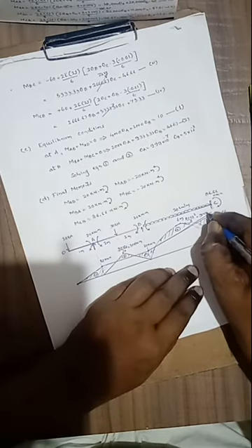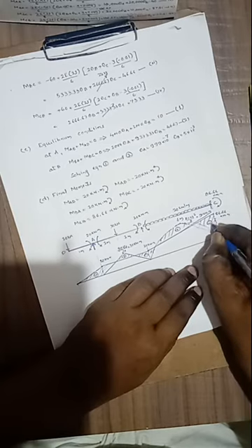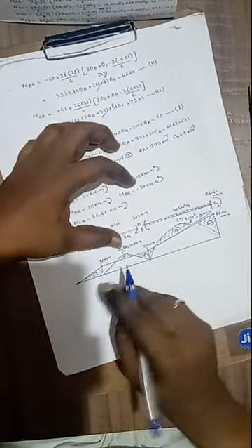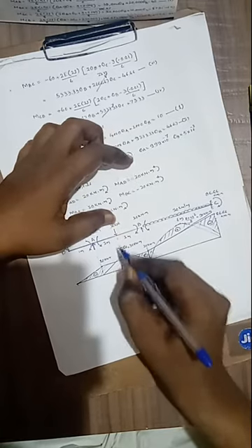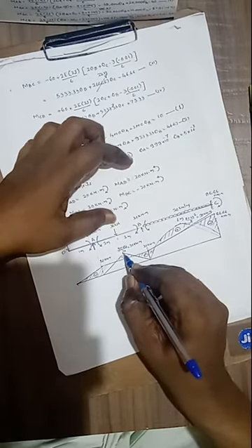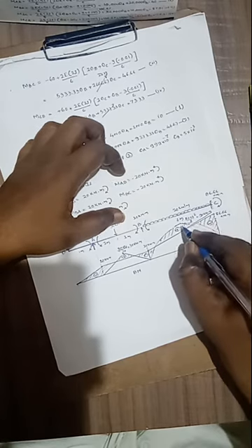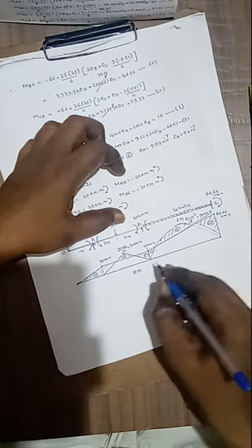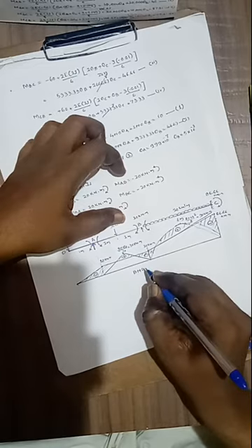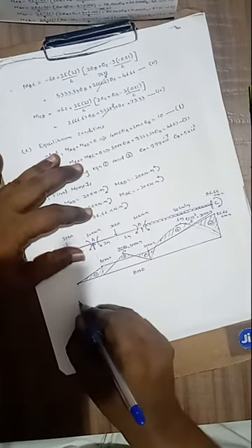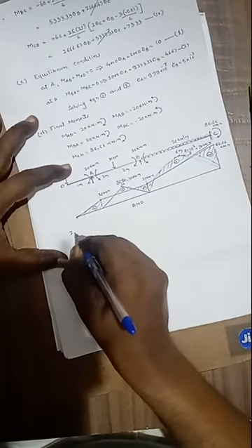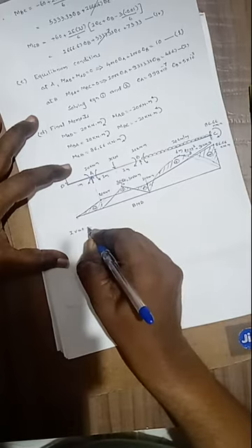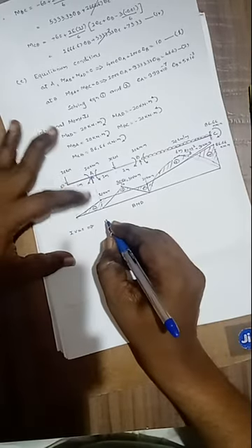Here this one is the bending moment diagram. These ordinates are negative ordinates at the support, and there is positive bending moment below the point load, that is 30 kilonewton meter. Here at the center the bending moment is maximum, that is 90 kilonewton meter. Then to draw the shear force diagram, here we can apply the equilibrium equations one by one. That one is summation of V equals 0. That you will get to draw the shear force diagram.